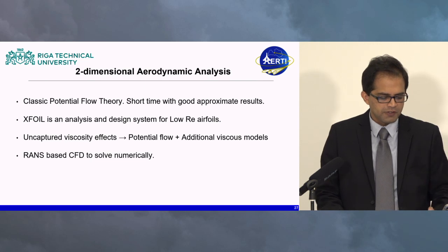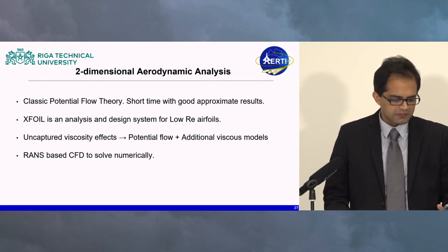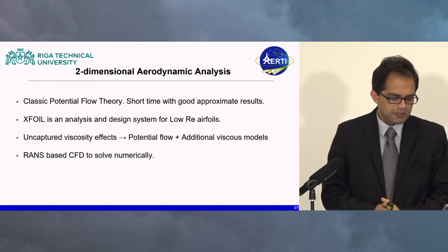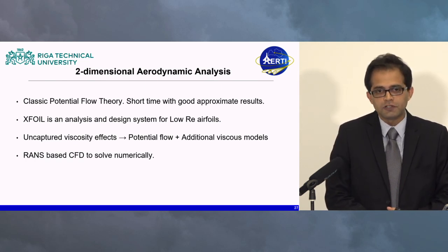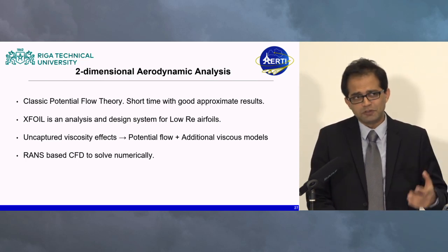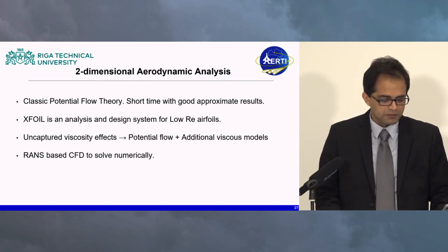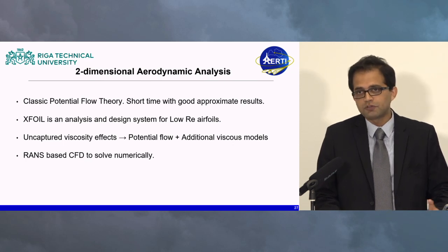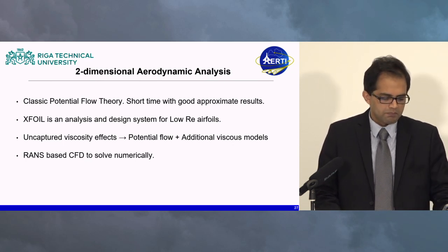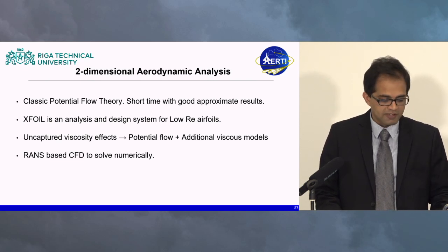Now for the design of the aerofoil, the classical potential flow theory is still valid and still applicable. And X-foil is a very famous and very convenient tool, and probably the best tool which is widely used for the evaluation of the aerodynamic characteristics and the performance of the aerofoils. Not only aerofoils, but also wings, aircraft, even the blades of the turbines and compressors as well.